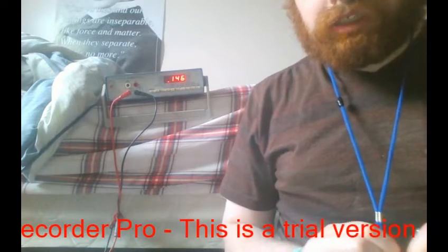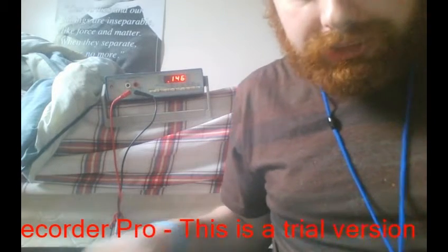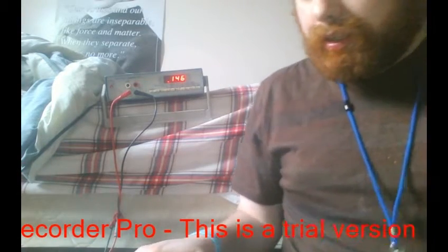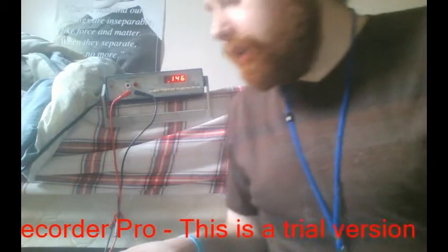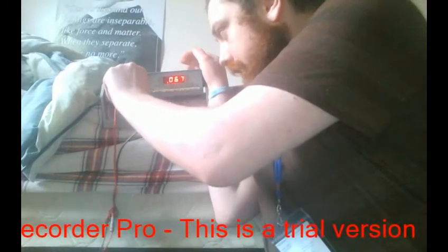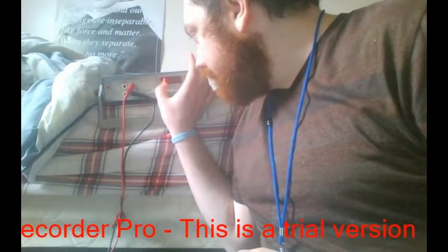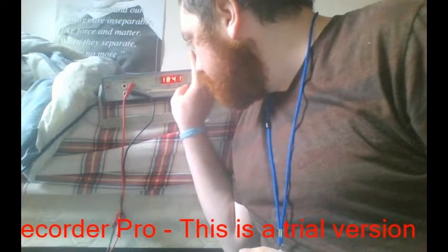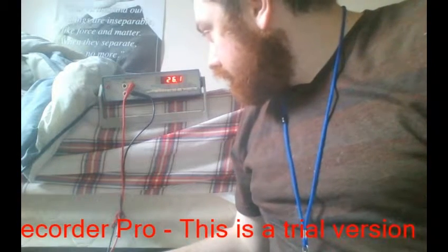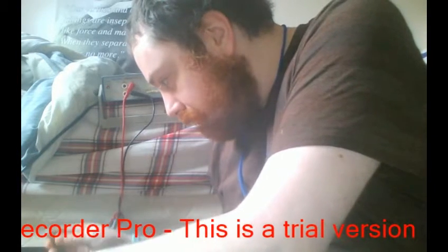First, you have to measure the voltage. These AC power supplies that put out AC voltage are not regulated, 99% of the time. So we're going to take the meter out of current mode, put it on AC volts, and go to the 200 range. Now it's measuring across the capacitor, which is not what I want to do.